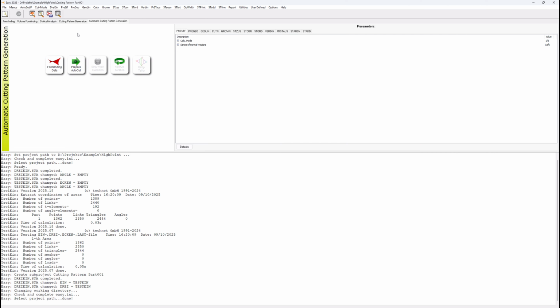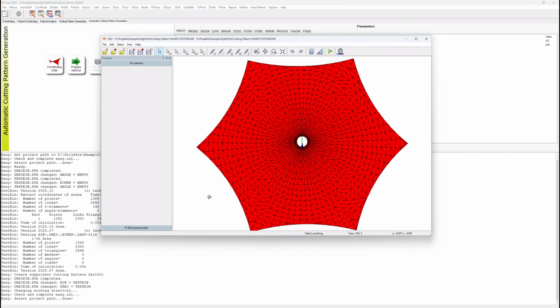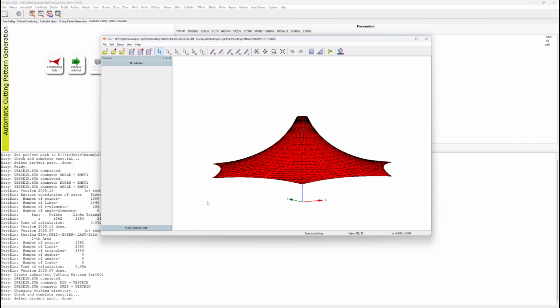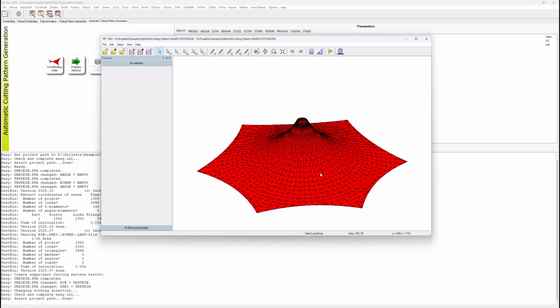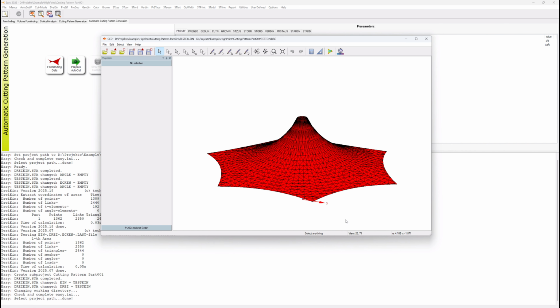Using the first tile, form-finding data, the input data can be graphically reviewed once again. In the case of our high-point membrane, the primary structure is already missing. It was removed during the procedure of creating the subdirectory and is therefore no longer included in the file. As part of this process, both the surface triangles and the file were renamed. The names of the opened files are displayed in the window header of the GED editor.